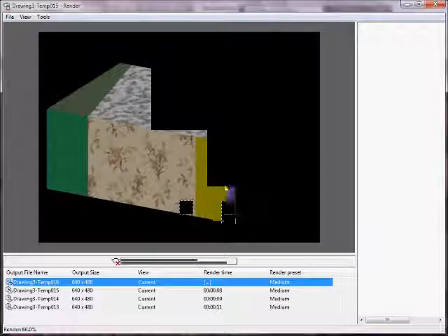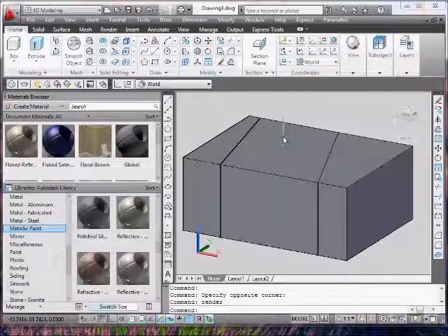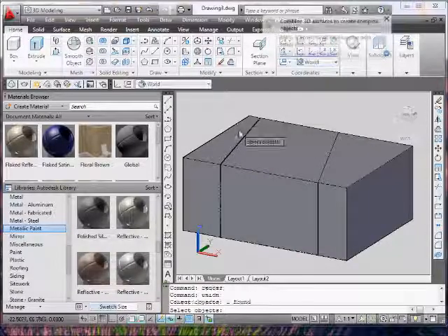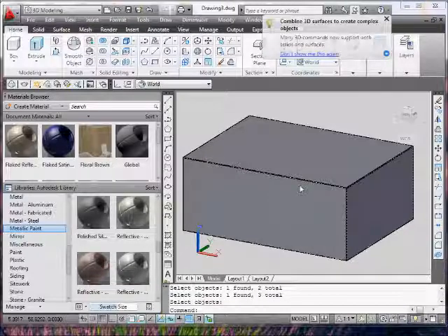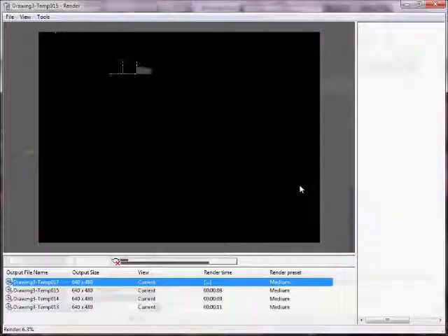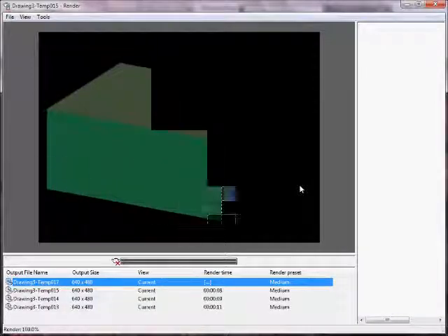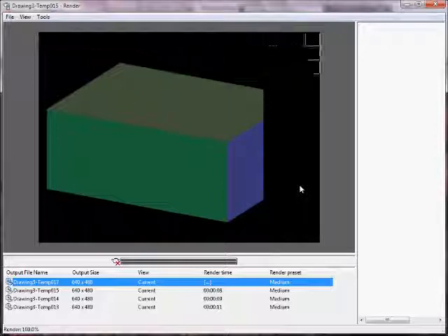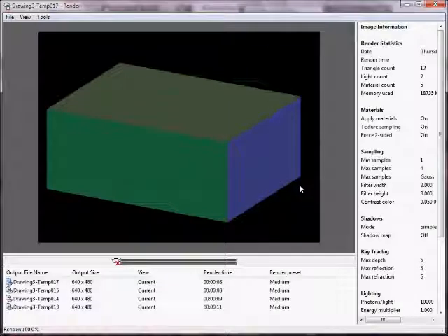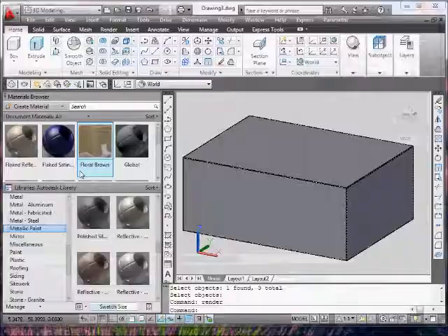But now if I unioned it, I select like so and render it, we lose what we had before. But the interesting part, it keeps the colors that you selected first. The blue one was always blue, so it didn't get changed at all. But the green ones were on the top over here and side. If I selected these first, these second, this one third, it all became the same color, whatever the first color you chose. So just keep that in mind.